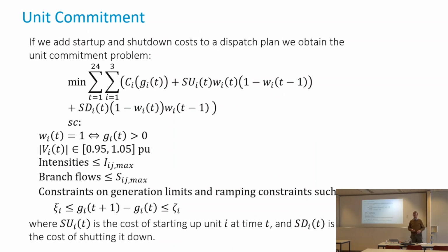Voila, so that's the interest of the DC approximation: it's tractable, so we can do very simple things with it. It also gives us a fairly simple explanation of why power is flowing when the approximation is valid. The approximation is valid in very high voltage lines, so typically transmission networks. The transmission networks are the backbones of the countries.